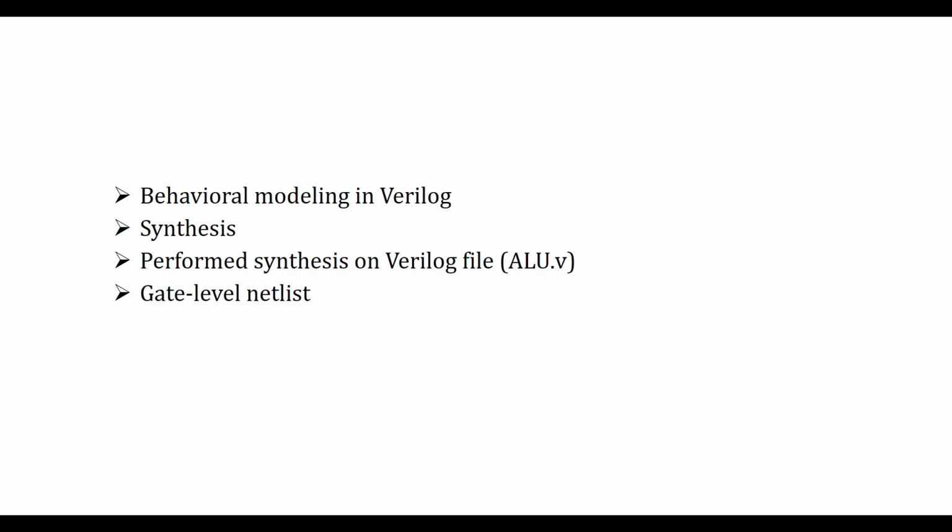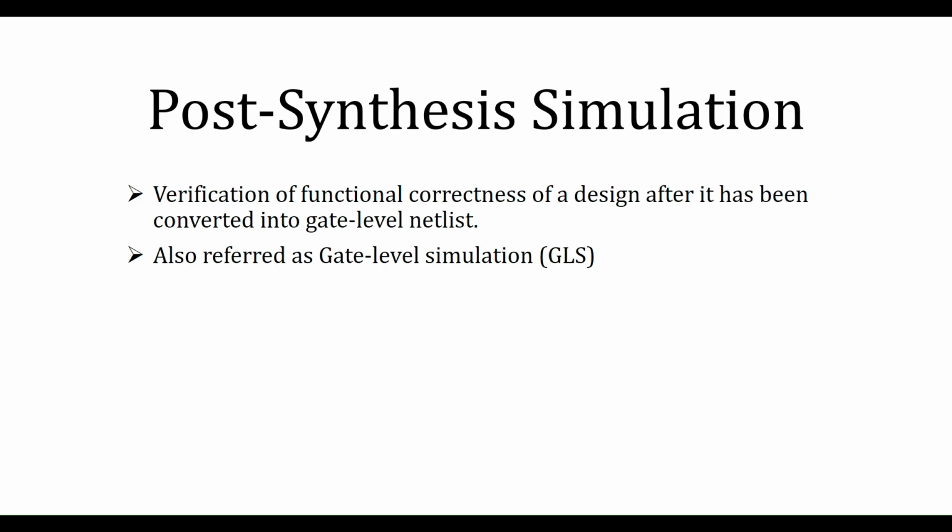We have discussed that. So post-synthesis simulation is a verification of the functional correctness of a design after it has been converted into a gate level netlist. It basically checks that the netlist we generated is logically the same as the RTL, and whether it is fault free. We will be checking this. It is also referred to as gate level simulation.